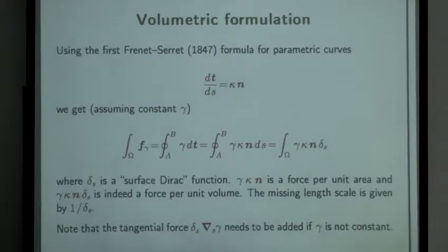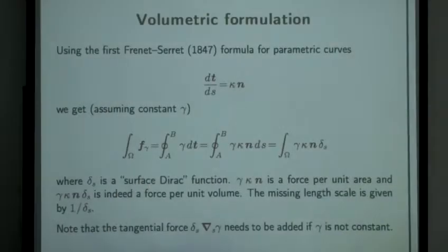Which is also itself problematic because you have a description which is volumetric, typically, like the level set function or volume of fluid, and you have to compute integral along a curve described by this volumetric function. So actually approximating this operator numerically is actually non-trivial at all. So you see there are a number of issues with this type of representation.